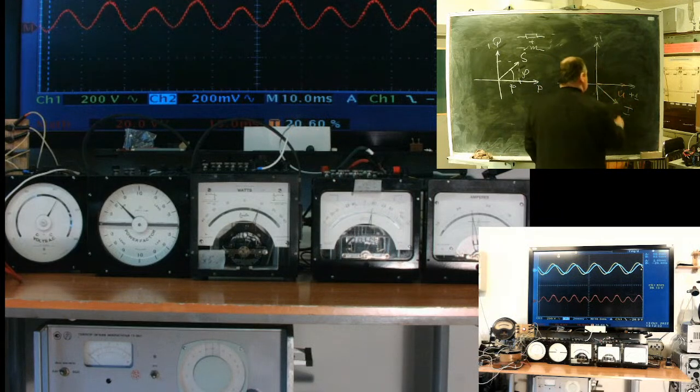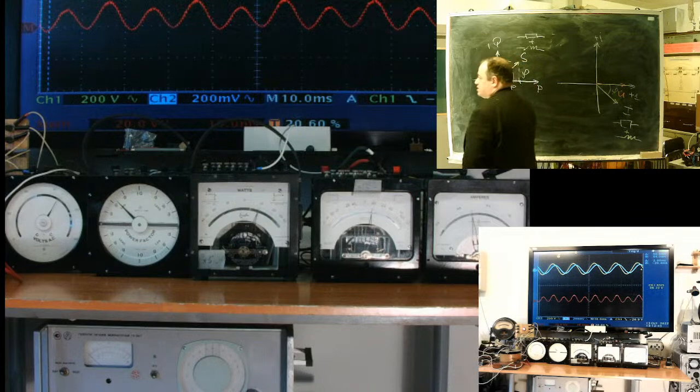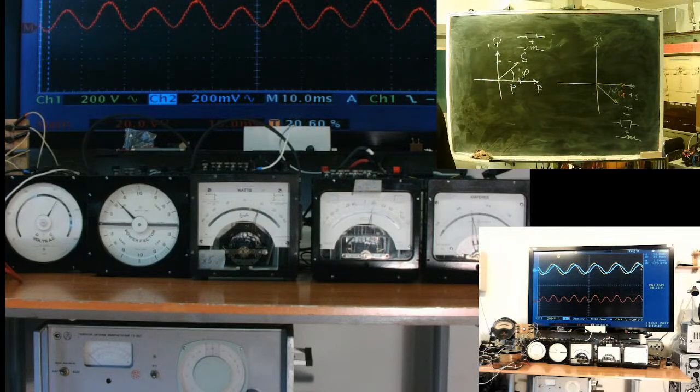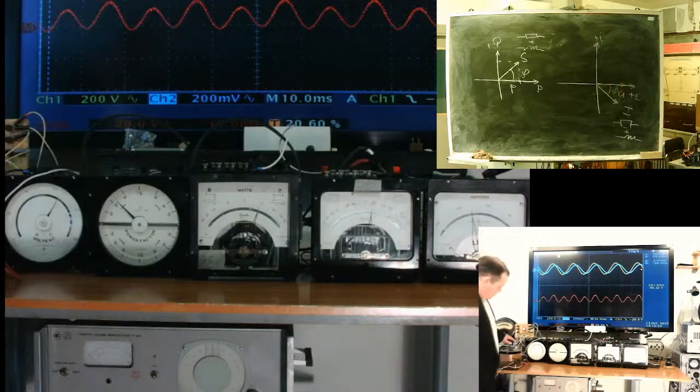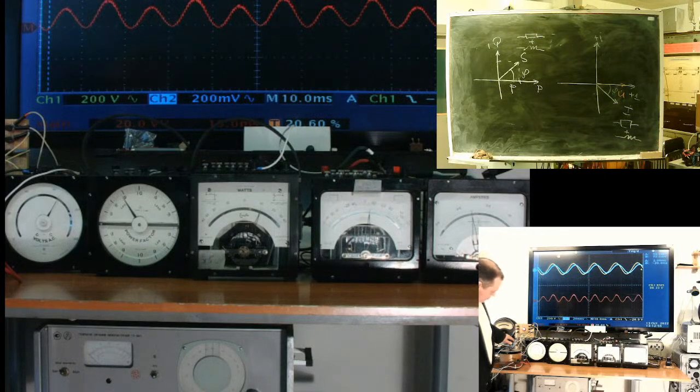Here is the current vector. Resistance plus inductance, resistance plus coil. Now I have a 45 degrees shift. It's not very usual. Normal cosine will be something like 0.85. This is the usual mode for networks.